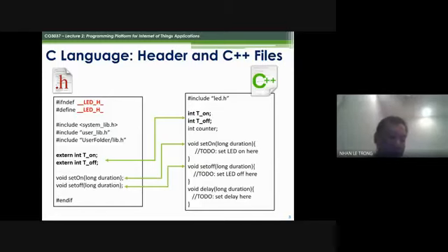The next one, I don't know if you normally work with this: you use the keyword extern to declare what can be used by other modules when you include the LED module here. You can have more than 2 variables, but they are all declared in the C file, and you extern them in the header file.